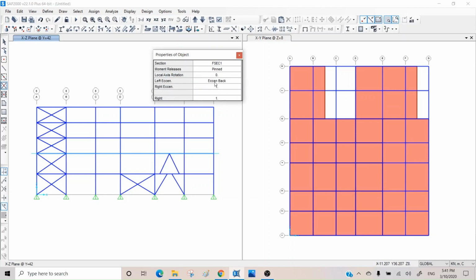So eccentric brace, again, you cannot see left eccentricity. The title is here, which is not correct. It should be left and right. So actually the first one is always left. So if I keep this one 1 and come here and draw, you see this gives me just left eccentricity. If I click here, now the wording is correct and the options are correct. So I have left and right eccentricity. So I can come here and choose right eccentricity and just draw it here like that.